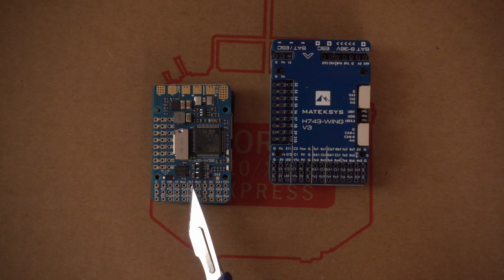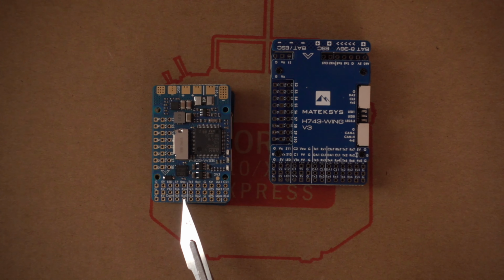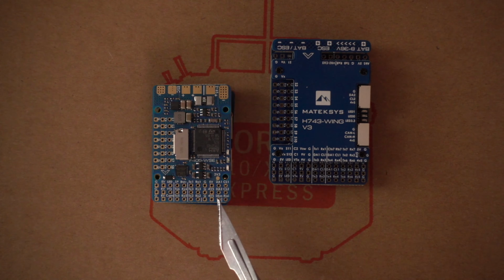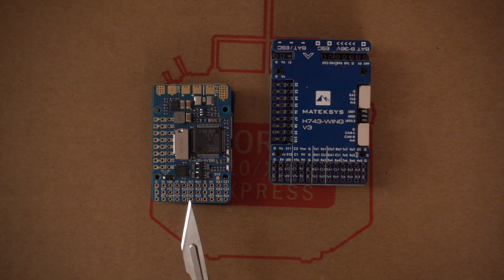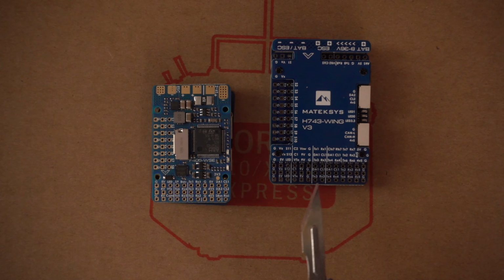So all these UARTs, we mentioned we have UART 1 here, UART 3 here, UART 2 here, and we can see TX and RX for 5 there, 6 there. They all basically work the same, so you don't have to connect a device to a specific number. The only reason we're connecting, say, a receiver to this one and a GPS to this one is for convenience of having this pad. They all work in the same way. The only exception being if you're using a FrSky receiver and you need to use an inverted pad, which you need to then use the one with the S-Bus. But that only affects these F4 flight controllers. The F7 and the H7, you don't need to worry about that.